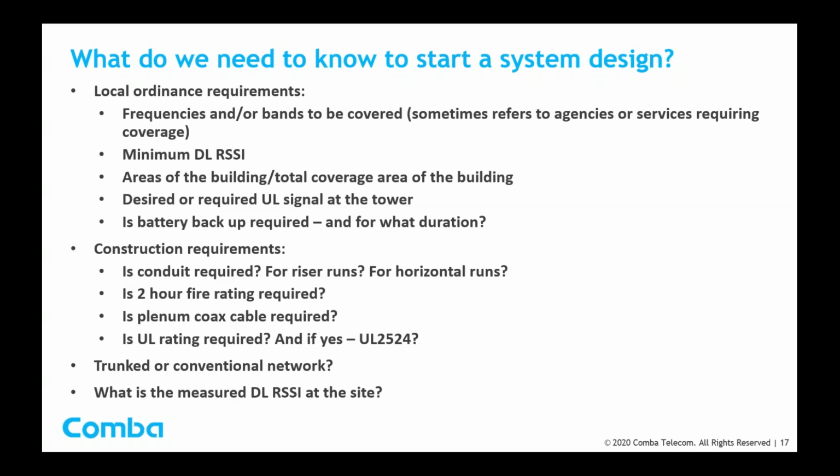So what do you need to know to start a system design? You need to know the local ordinance requirements. You need to know the frequencies of the bands to be covered. And in some ordinances, remember I mentioned earlier, they don't always know the exact channels and things. I've seen ordinances that say the system must support the local sheriff department. Well, okay, that's good to know, but what does that mean from a technical perspective? It means you need to find out what channels and what bands the sheriff's department runs on.